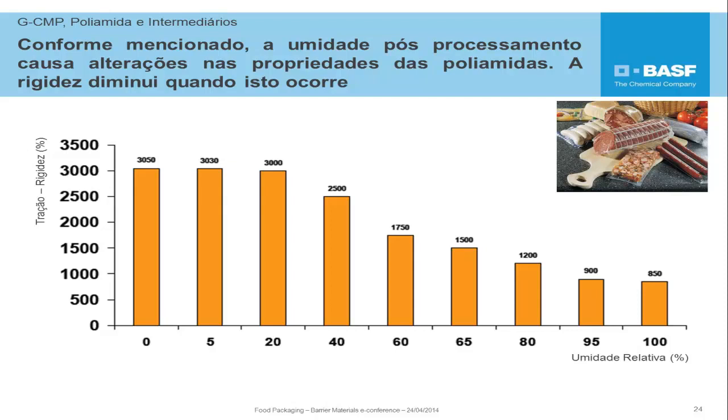And we see the fall of tensile strength, which is noted as a result of the effect of humidity between the polymer chains. Therefore we see, in general, an important effect of improvement of properties by the increase of humidity. Although our focus in this event is food packaging, it is interesting to comment on the effect of humidity on applications of injected polyamide parts.